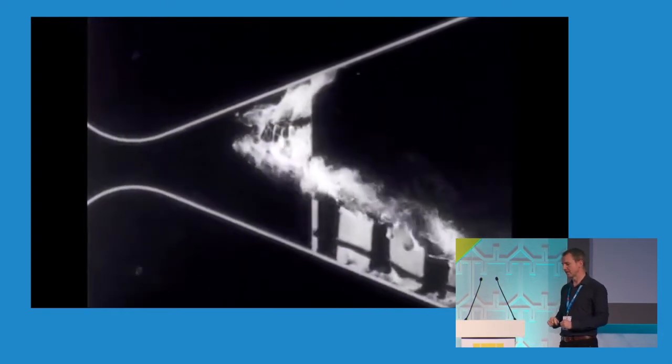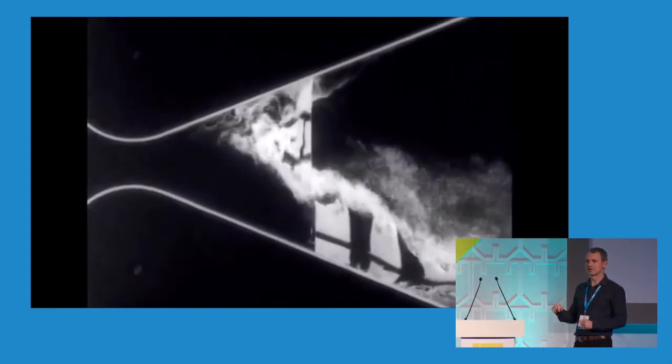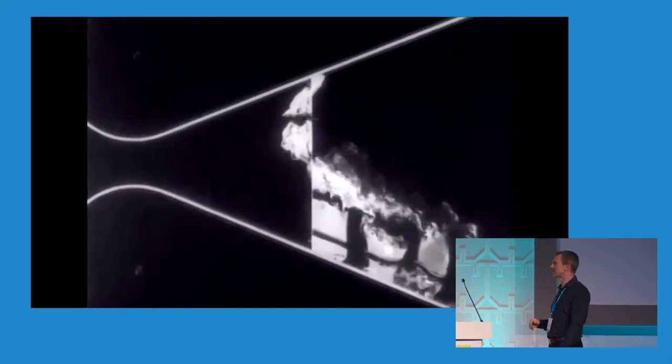And I guess this is where I was going to finish, really. One of the key lessons to think about is that it's not just the positive pressure that creates an issue. I'm thinking about, obviously, buildings being subjected to huge forces from high wind speeds. But actually, the vacuum that can be generated could be just as problematic as well, and that can occur in areas that you might not expect. I think we've probably all seen the accumulation of litter or leaves in entrance foyers to buildings. And that's exactly because what's happening is what's shown in this image, that it is being recirculated past an abrupt edge. So I think that's a really interesting observation and thing to take forward.